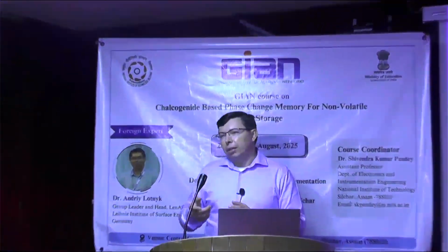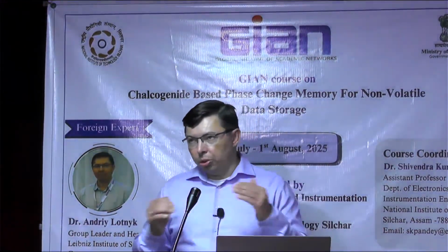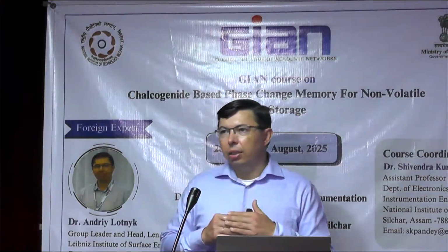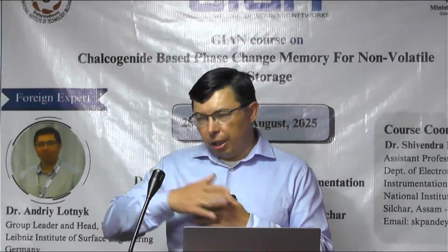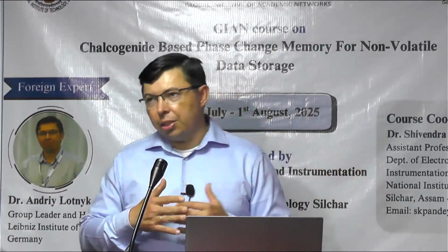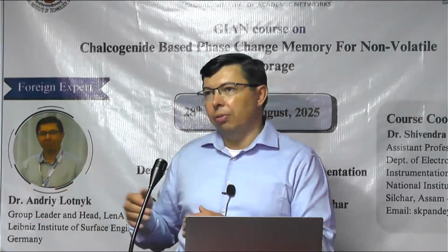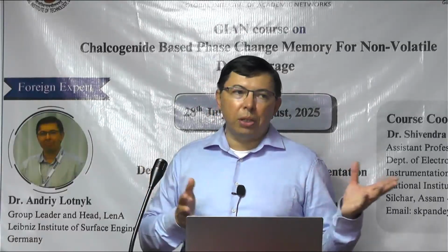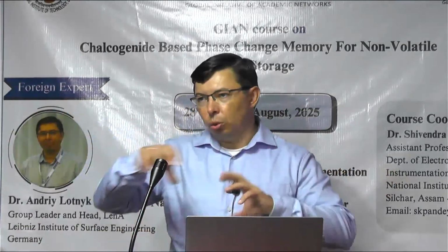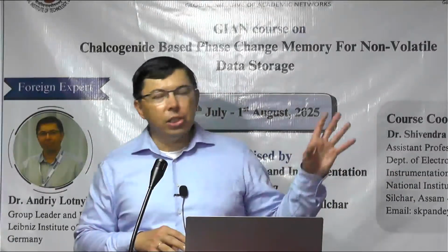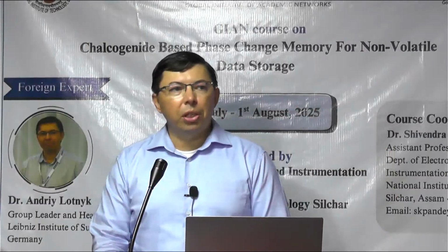But if you want to use the electrical switching, of course you don't need to deposit the protective layer. Then either you etch the oxide and then deposit the contact directly, or in another system, like we do, you deposit the contact directly in another system. Because in a magnetron system you can change different targets, and then you can deposit it. But this is just to know about this issue. So it's a big issue.